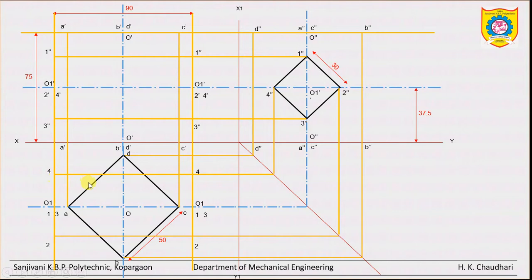Okay, now see, we have to observe this intersection from the front side and the top side. So first locate the points of intersection, these 4 points. We can label the points P2, Q2, and similarly here P4, Q4.